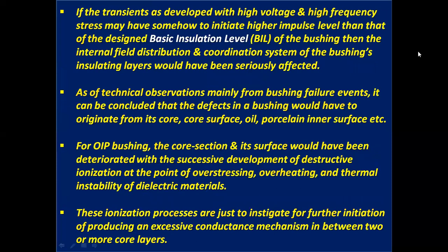If the transients developed with high voltage and high frequency stress somehow initiate a higher impulse level than the designed basic insulation level (BIL) of the bushing, then the internal field distribution and coordination system of the bushing's insulating layers would be seriously affected.